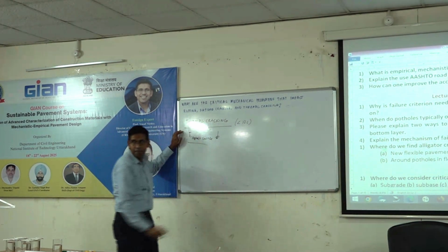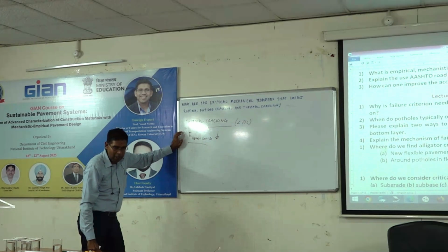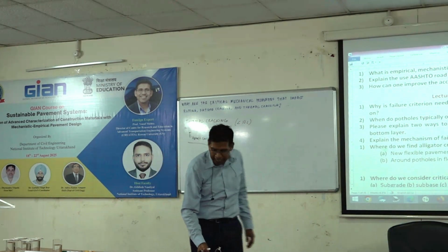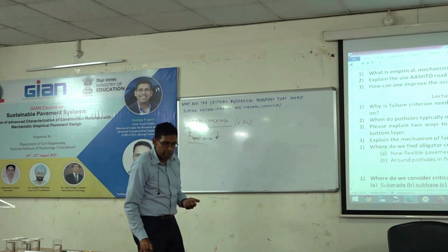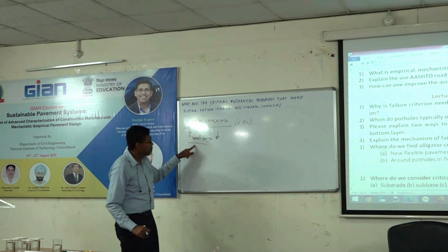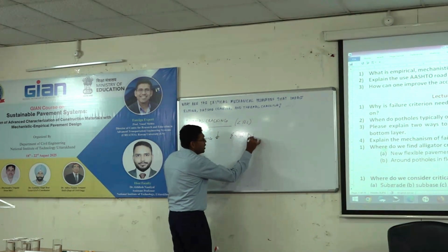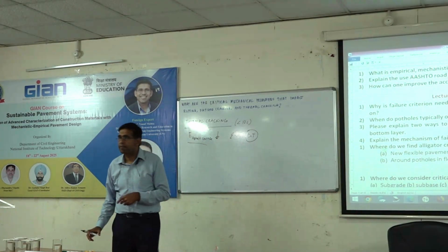What else? We discussed this a little bit a while ago. What are the other parameters that will impact thermal cracking? So you have asphalt concrete, due to the cold front, right? When you have a cold front, you have thermal contraction, alpha delta T. Delta T is the temperature drop, correct? So alpha is the coefficient of thermal contraction. What else?